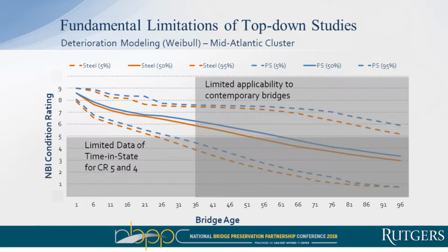The problem is all those bridges are different, right? So at some point we didn't use epoxy-coated rebar. Now people are maybe not going away from that. At some point we didn't have UHPC or HPC or pre-stressing or different types of steel coating, or we didn't use continuous bridges. And so bridge practice changed, right? And so if you look at a bridge that was built 30 years ago or 35 years ago, it's not the same as the bridge we build today.